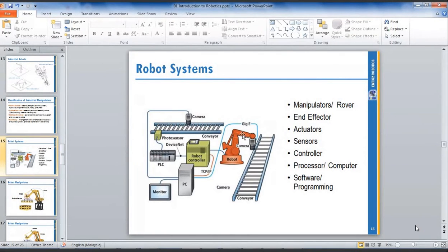All the motion of the robotic arm uses that calculation, whether DH method or homogeneous transformation matrix. Because you want to move from point to point, for example from point A to point B. To move from A to B, we need an algorithm, a formula like the DH method or homogeneous transformation matrix.